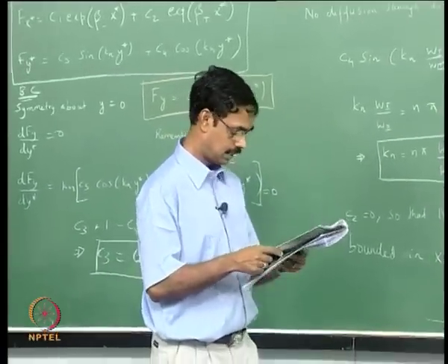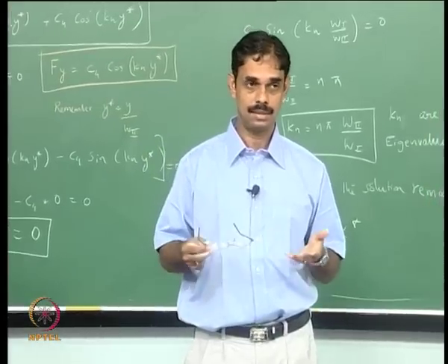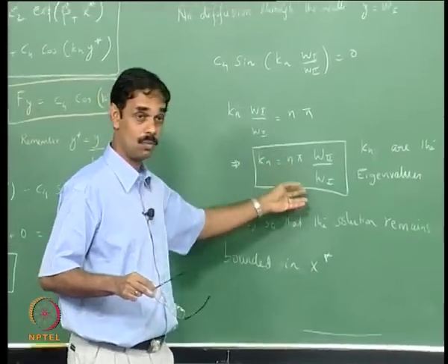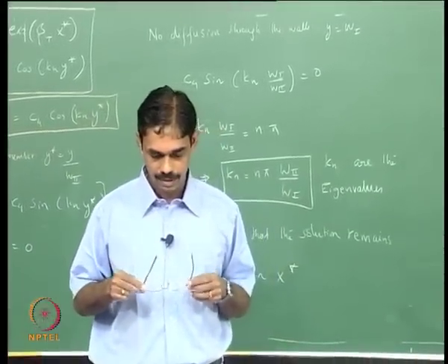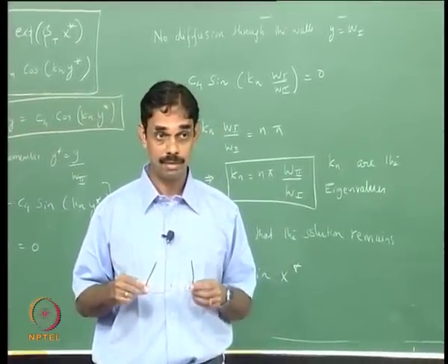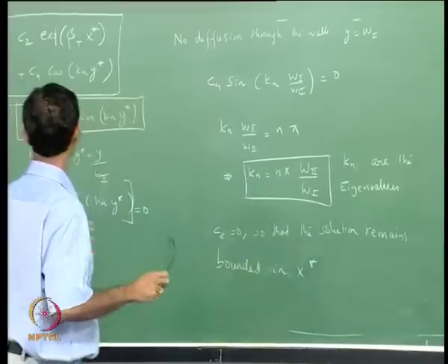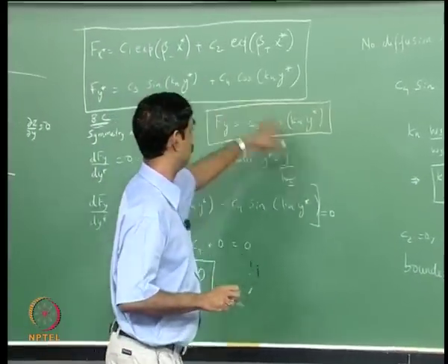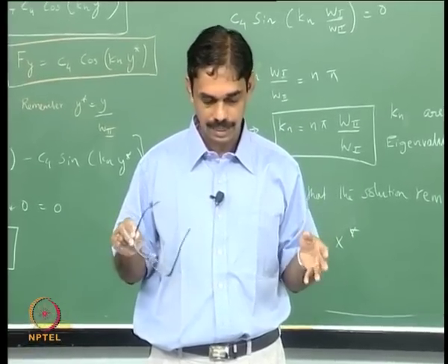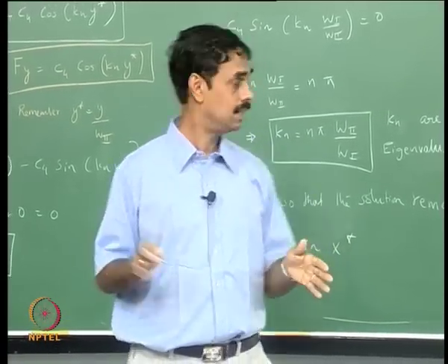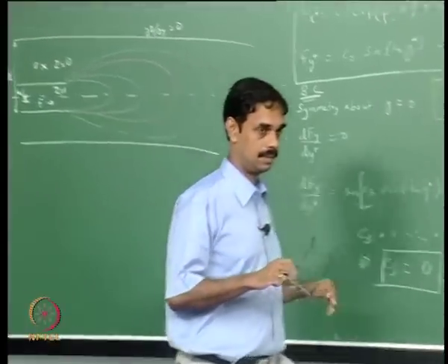So since Kn takes infinite values, that is, there is no upper bound on what n is, the solution to Z0 is an infinite sum over all integer values of n with coefficients which are like C1 times C4. These coefficients, and we are adding n number of them, have to be solved using the boundary condition at the inlet plane. Okay, so it is clear, right?